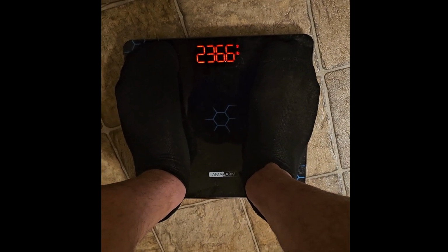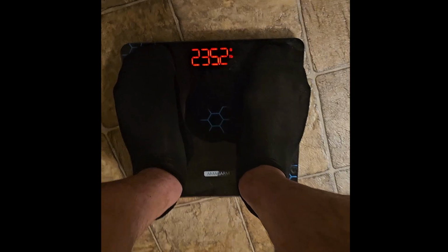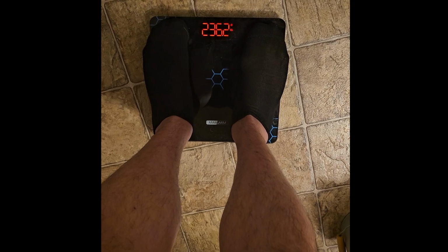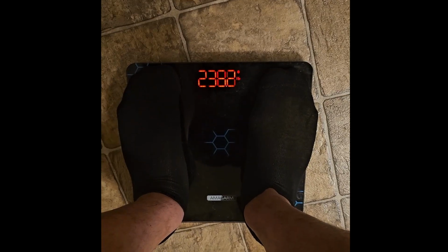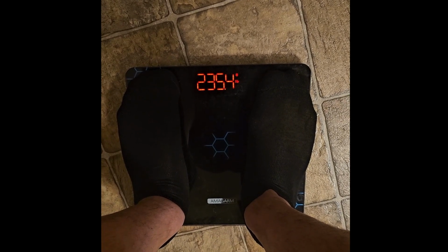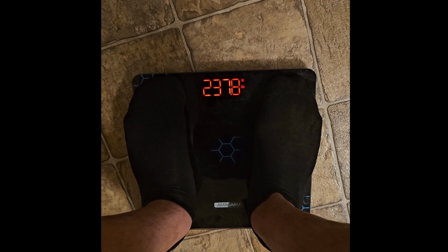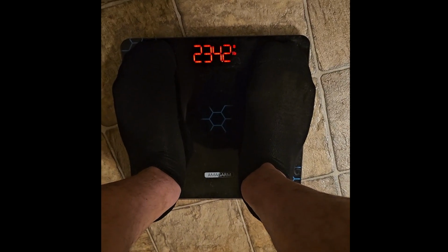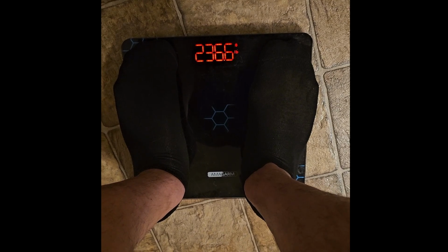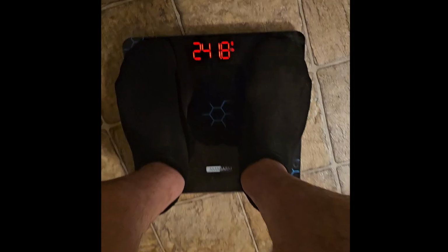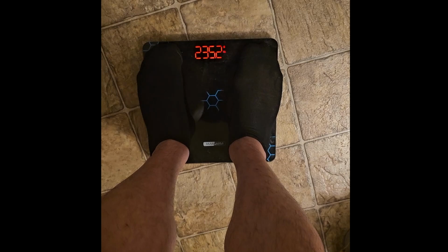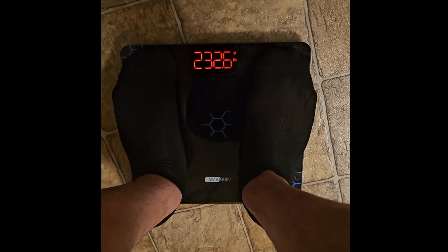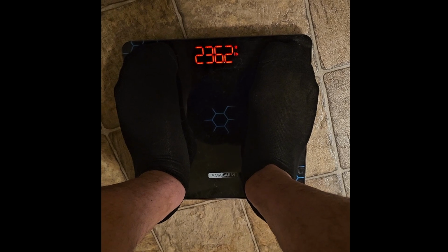So the same thing happens with the car. As it accelerates up, you get an increase of normal load. As it reaches the top of the movement, acceleration actually has to reverse, where you get a drop in your normal load, and then you settle again at the load of whatever your static weight was to start with. So basically, my model is kind of demonstrating this, but in car form.